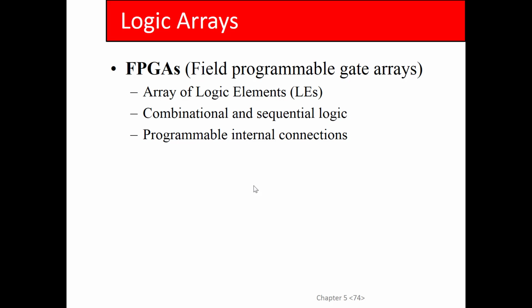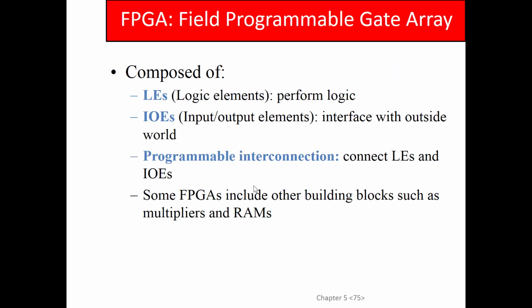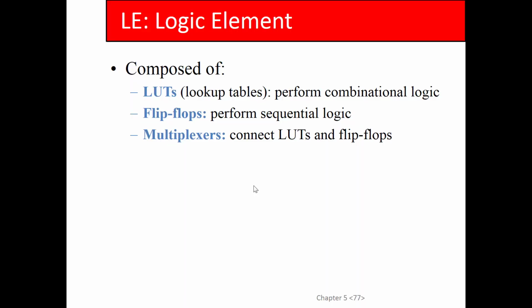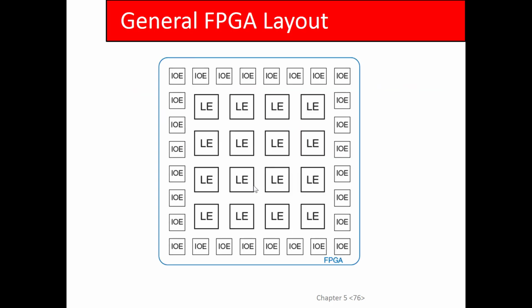Okay? The way it works, though, is it uses little tiny LUTs, lookup tables, which is just a fancy way of saying RAM. They're just little SRAMs. And when I say little, in current generation FPGAs they're 128 entries deep by 1 bit wide. But configuring that RAM allows you to create what is essentially a customized logic gate.